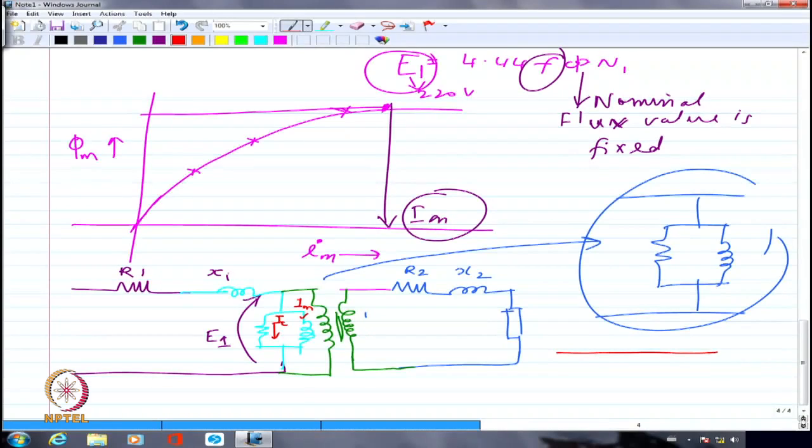So if I show this as the voltage applied to the transformer, for example, I am going to have whatever is my IC somewhat like this, which will be in phase because it is resistive current, right? And I am going to have the other current as inductive. So I should show maybe my inductive current somewhat like this. I am drawing all big things. Really the currents are very small, but nevertheless, I am just showing it for the sake of it.